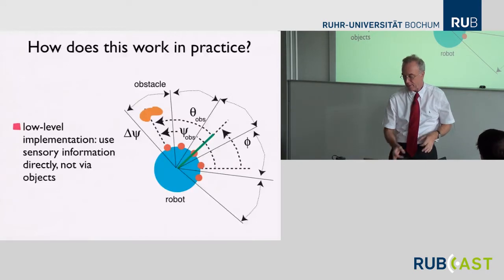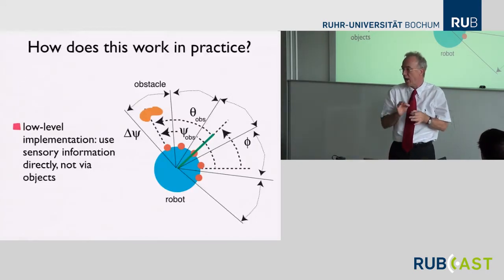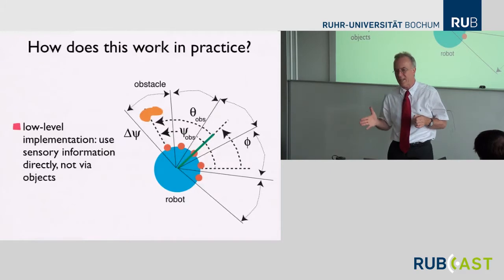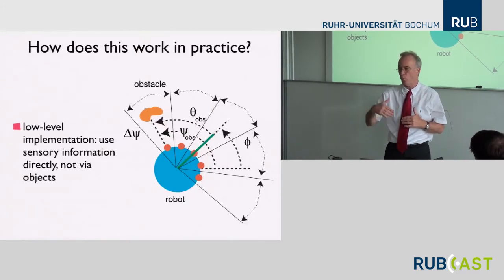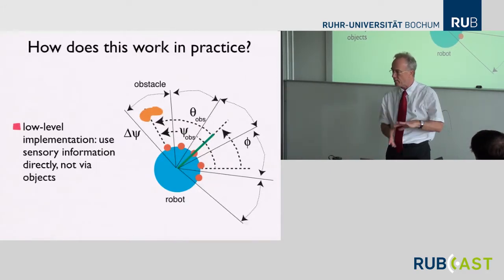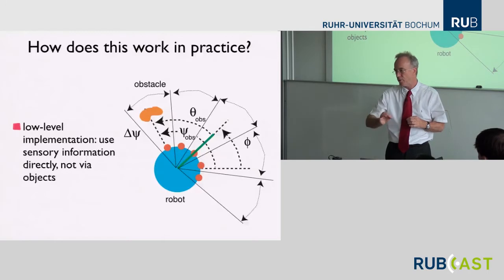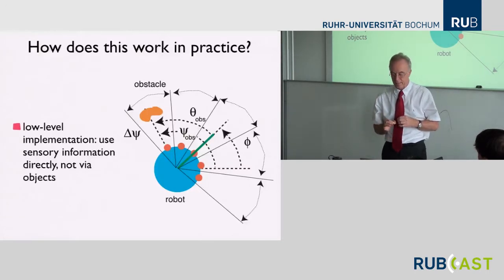And the additional parameter to tune now is really how quickly the repulsive force falls off with the distance. These infrared sensors turn out to be quite short-sighted. They only see about one vehicle length. That's why it drives around somewhat awkwardly. So when it's farther from a surface than one vehicle length, the repulsion strength goes to 0, and it has no obstacle there.